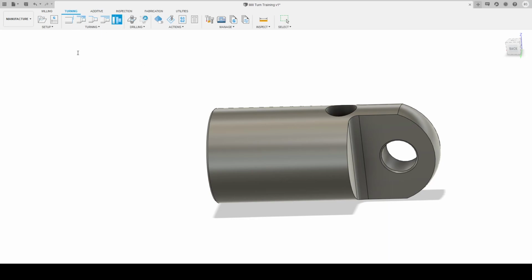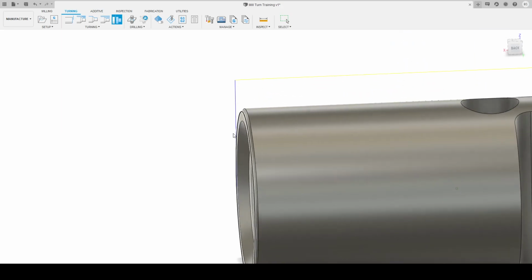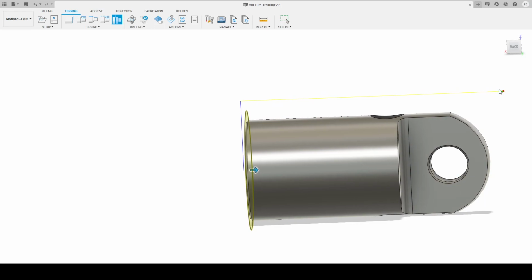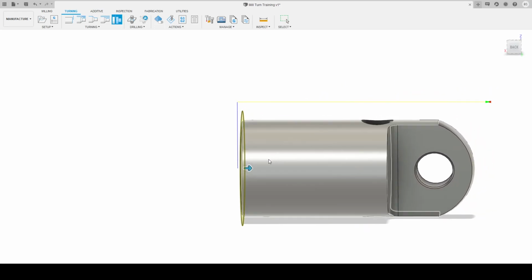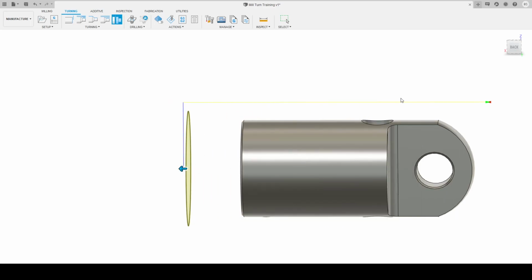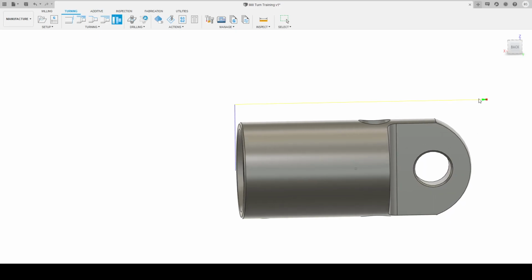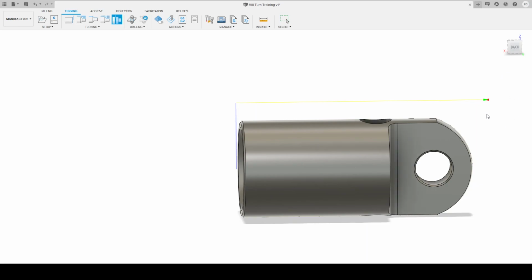Post processor, we'll give it a unique tool number, click accept, click select, and then it's smart enough to already know what we want to part off because it looks at the model at the back. Again, you can manipulate this, you can grab the handle, you can part off anywhere, but we want model back with a 0 offset. You can do reduced infeed and speed on your part off if you want, so once it gets to a certain X diameter, it'll reduce the speed and feed. Very handy. Linking, we don't really need to do anything.